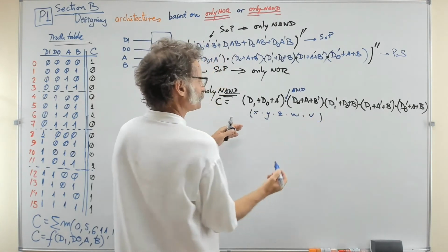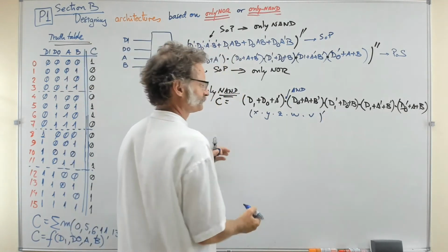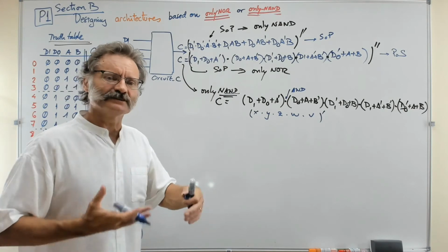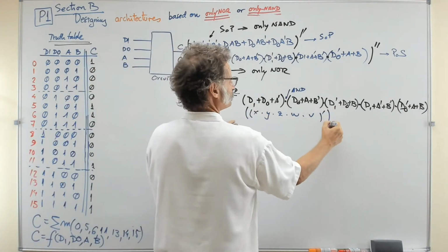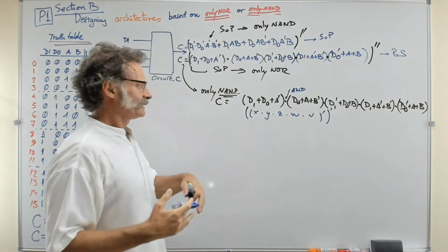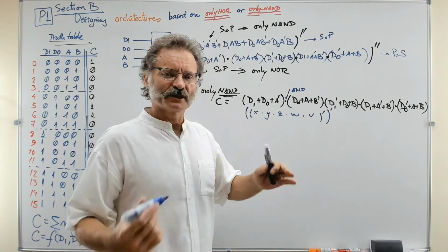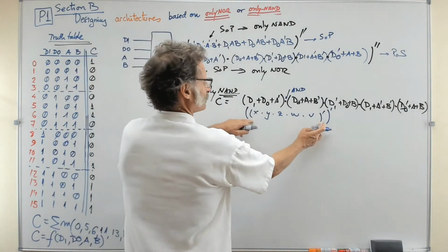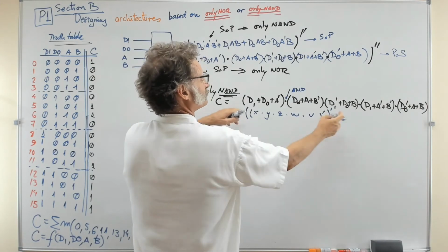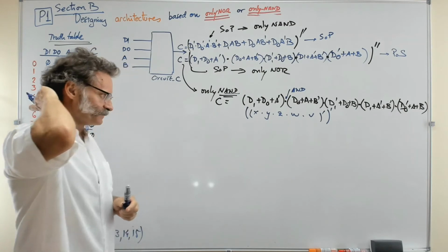So what you can do to get a NAND is simply invert it. You invert it one time, and then there is another gate that does the job of keeping the logic expression the same, but using two NANDs, you see? The first one here, and the last one, which is a NOT. That's a way to do it, okay?